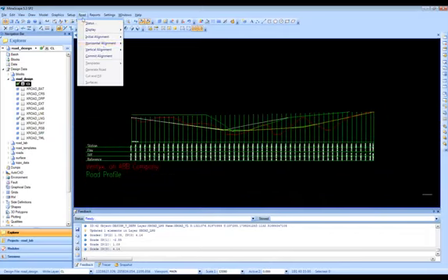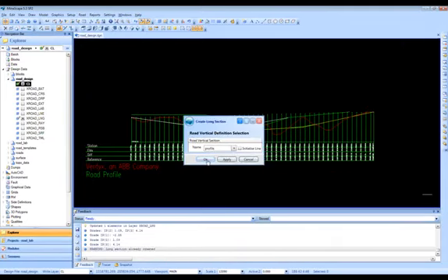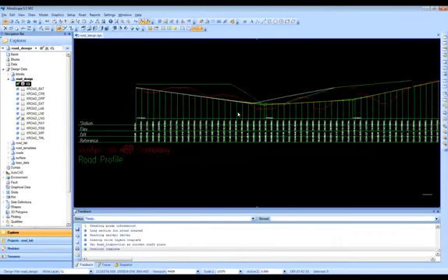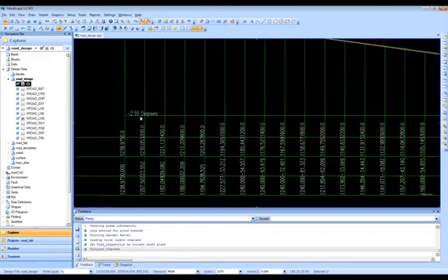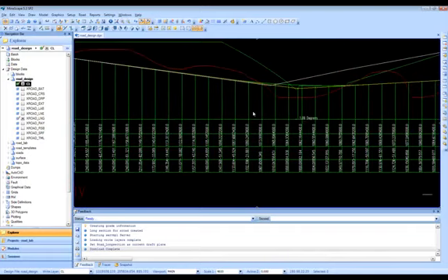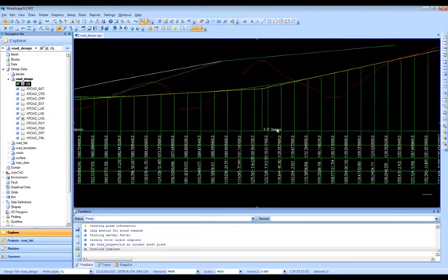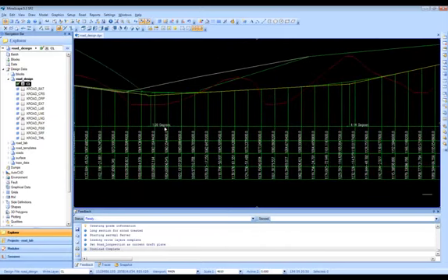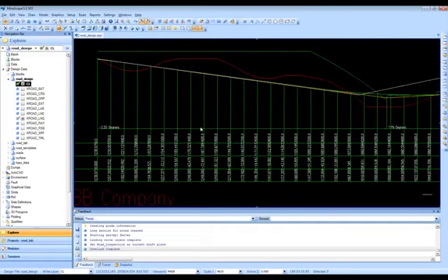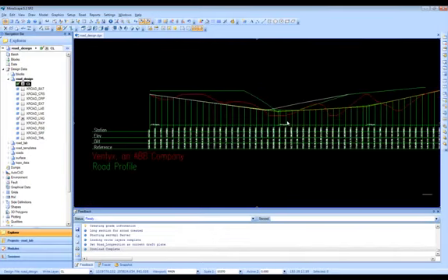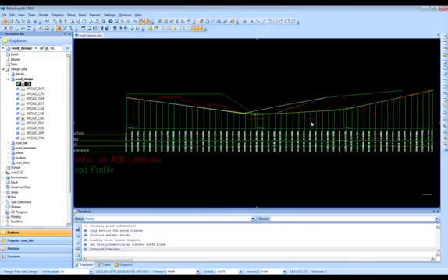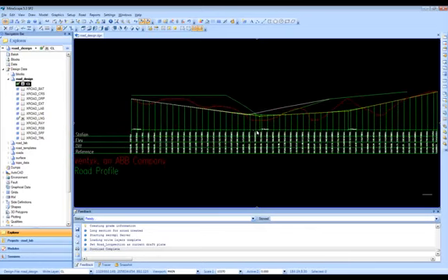Now that's kind of what I have. So if I go to road, vertical alignment, and I do another long section, I've asked for some grade information on my long section, so this gets updated to what grades I do have. So 4 degrees, 1 degree, and then minus 2.56 degrees. You can show these either as degrees or percentage, depending on what your current project units are set to.